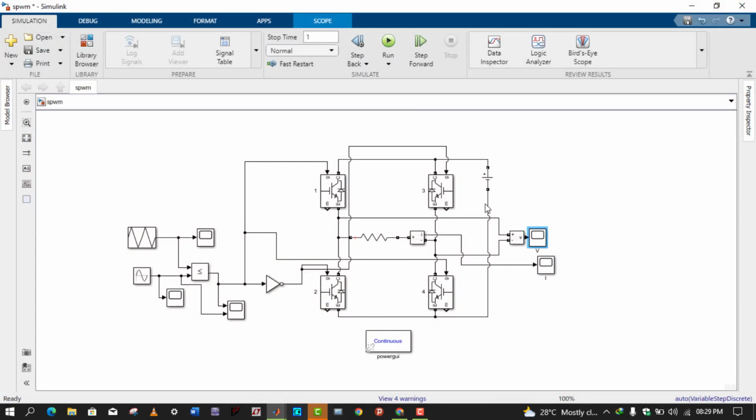So the significance of this inverter is that we can get sinusoidal output voltages, and we can run our loads smoothly. This inverter is mainly used in the market, and we get a pure sinusoidal waveform in the output. The working principle is very easy. First I generated the complementary waveforms for these MOSFETs and those MOSFETs, and then just by running the H-bridge and connecting the outputs, we can get our output waveforms.